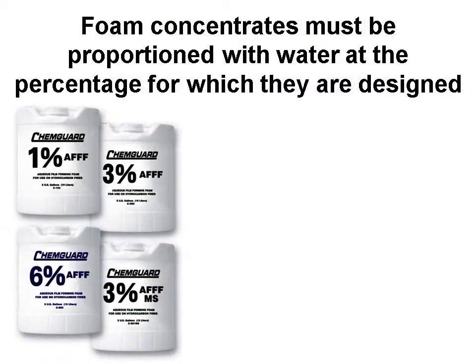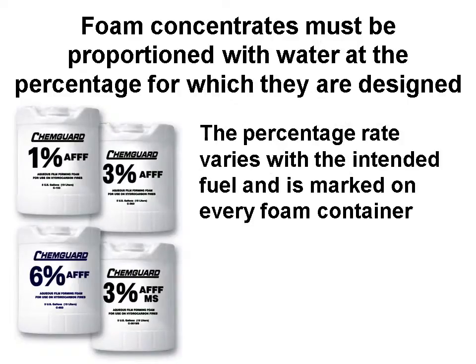Foam concentrate must be proportioned with water at the percentage at which they are designed. Most of them, if you look at the buckets that the foam comes in, will say on there what percentage to use. The percentage rates vary with the intended fuel and are marked on every foam container. Most firefighting foams are designed to be mixed at 3% to 6% concentrate in water.